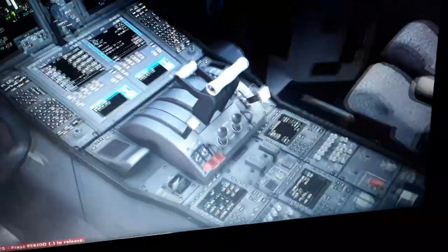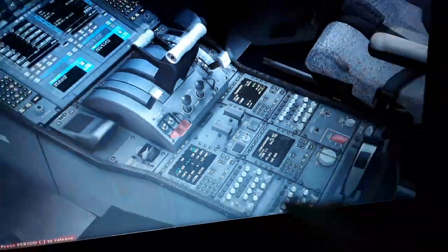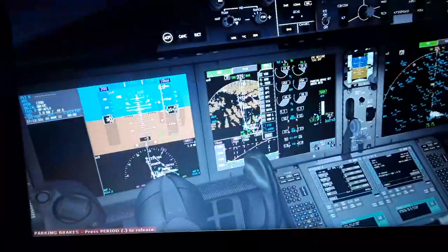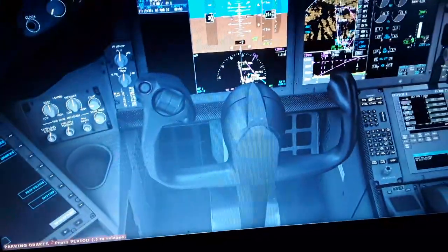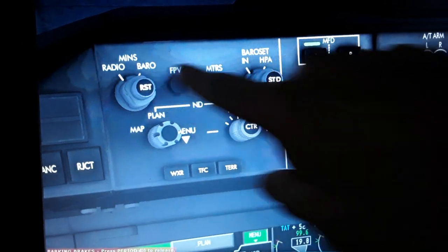You can see a few things. We have the fuel control, left and right switch. You can turn off and on the engine fuel flow, left and right engine fuel control, fire extinguisher, left and right engine, transponder, rudder trim, radio and communication panel over here, the mouse pad here to control all the screens. You can see I told you about the horizontal trim stabilizer, autopilot disconnect, head-up display, also declutter switch. We have also the barometric pressure setting from the AFS panel. Over here, inches of mercury, hectopascals, 29.92 now, minimums.